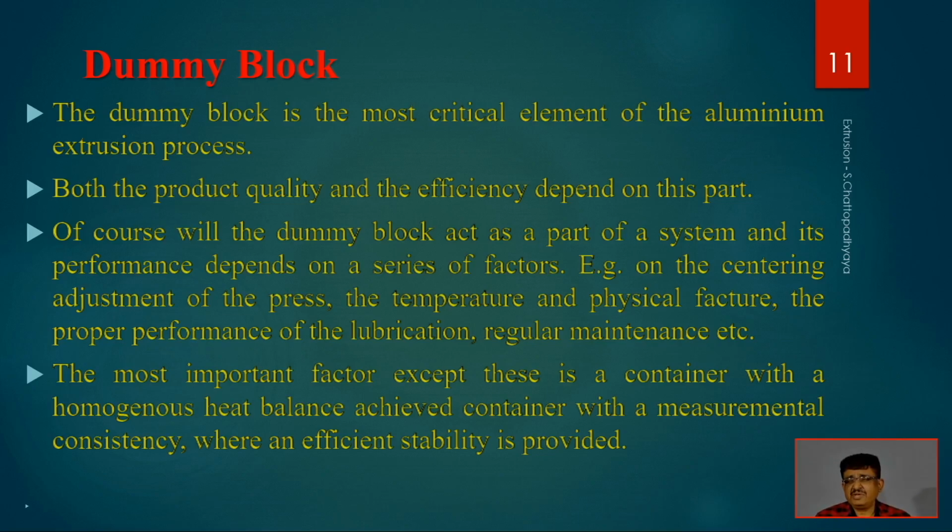And then the temperature and the physical features associated with that, and lubrication also, how lubricated, and regular maintenance. The biggest advantage in maintenance is that if at any time the dummy block gets adhered with heated aluminum oxides or that kind of aluminum product, one dummy block can easily be detached and another installed. So online maintenance is possible, and the changeover becomes easy without much problem. If the entire plunger and ram had to be replaced because of the adherence of the extruded billet material, it would be cumbersome.